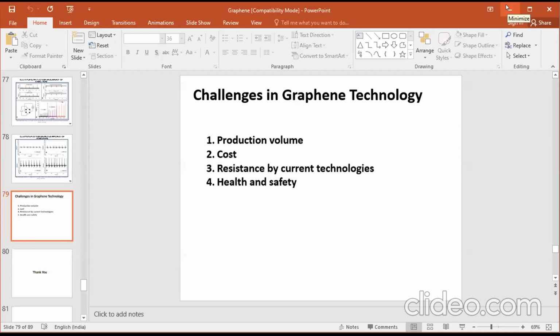If you want to, you can just transfer this CVD graphene to any polymer surface. Suppose you want to transfer it onto a polyethylene terephthalate (PET) sheet, that can be easily done. You have copper with graphene. You just deposit a PMMA solution, spin coated. Then you etch out the copper. Now you have the graphene PMMA sheet. Now you can transfer that to the PET sheet, right? Just dissolve the PMMA in acetone, then you can transfer it to a PET sheet. So that way we can transfer to a polymer surface also, right? So that's possible.